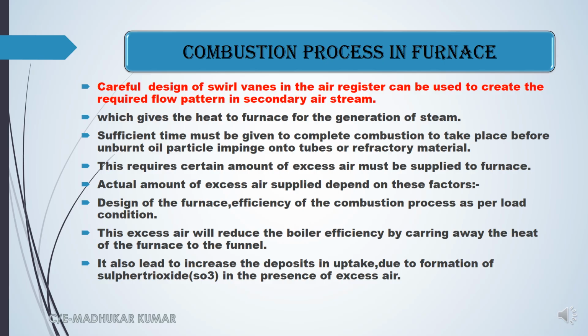It also leads to an increase in deposits in the uptake, because along with that the flue gases also go out, and with that any unburned fuel carbon particles also go up and create deposits in the uptake. And this excess air gives excess oxygen to form sulfur trioxide, and this trioxide also creates a maximum of deposits in the uptake. So in this video, I have basically discussed the complete combustion process in the furnace.